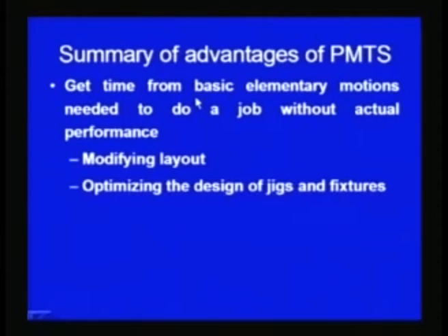It helps to get the time from basic elementary motions to do the job without actually performing it, which in turn helps to modify the layout and optimize the design of the jigs and fixtures, so that the time required for carrying out the job can be reduced. It avoids the subjective rating which is normally associated with work sampling and time study. Here the subjective rating is not a part of the PMTS system, and it is not decided by the judgment of the time study man or the work study man.